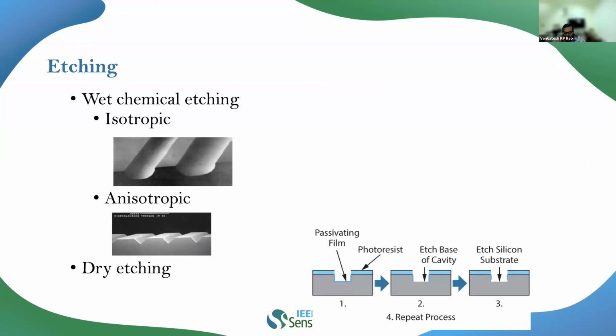On the other hand, whenever you want to realize any of the suspended structures, deposition alone will not work out. If it were integrated circuits, the CVD deposition would have been fine. Then for any of the MEMS structures under consideration, we have micromechanical structures associated with it. So we need to go forward for the etching process.